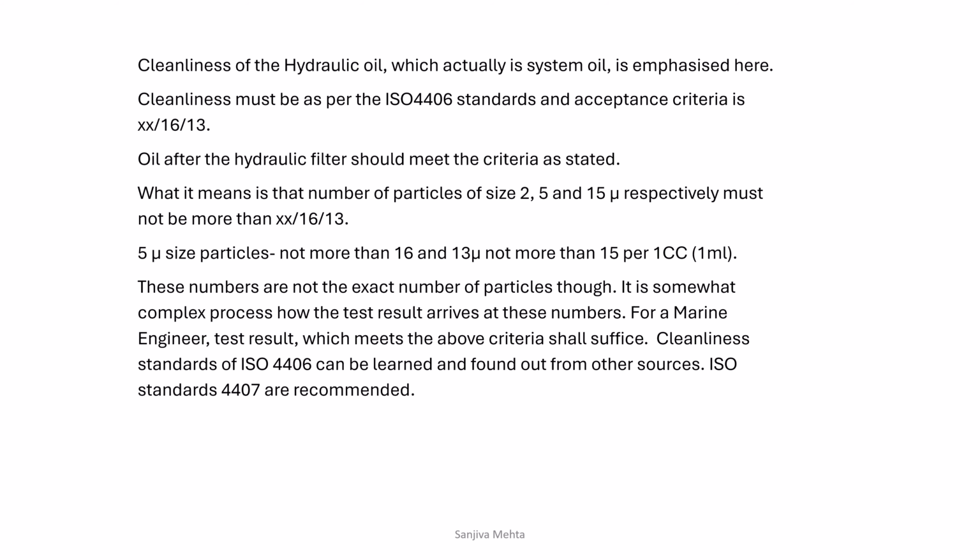So cleanliness of the hydraulic oil, which is actually system oil, as I was telling you, is emphasized here and must be kept in mind. Cleanliness must be as per the ISO 4406 standards, and the acceptance criteria is XX/16/13. Oil after the hydraulic filter should meet the criteria as stated.